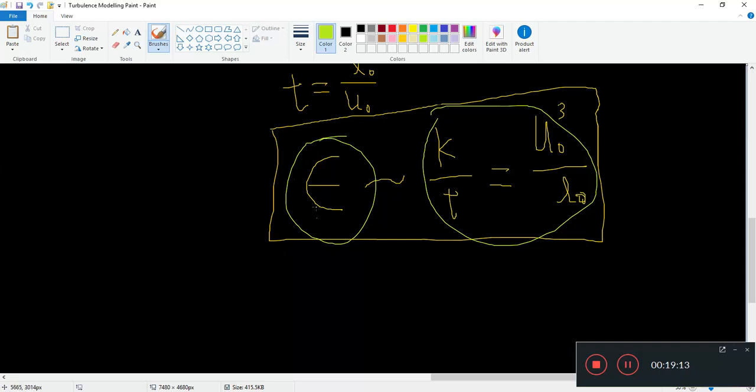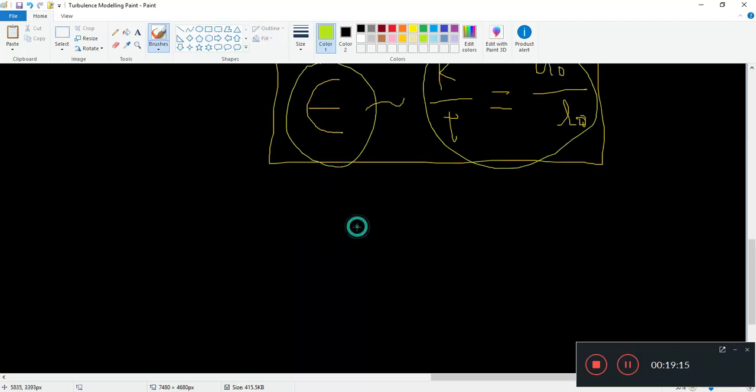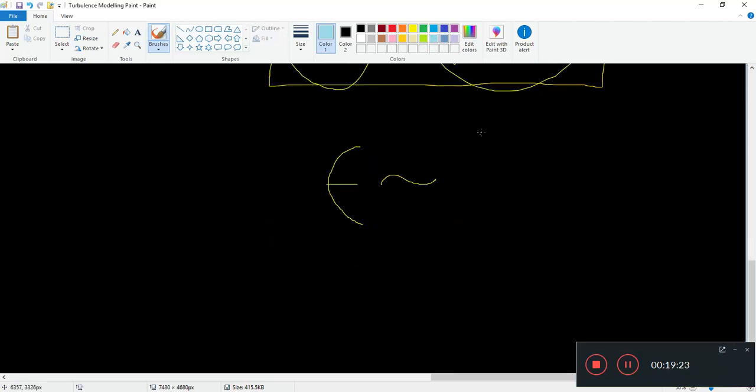And how do we characterize this dissipation rate? I'm going to say this dissipation rate epsilon will scale as some kinetic energy at the Kolmogorov scale, smaller scales, for which we like to use the term eta.